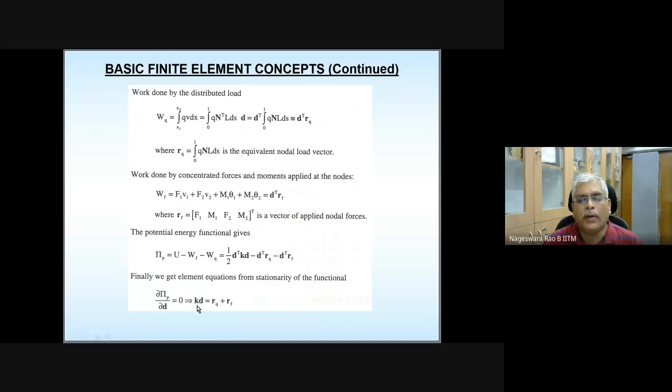So finally, this is what you get: KD equal to some force vector. And here the force vector comprises contributions from the distributed load and concentrated forces. Please note that whatever we derived, this element equation system is a general one.